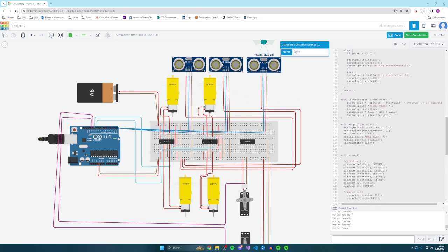The stop is called when the front locate is under 5 inches away. We can see that here, and then it will stop the motors, give us an end time, tell us the end time in milliseconds, and then call the calc distance, which will then take this and using some math, calculate this all based on the distances called.